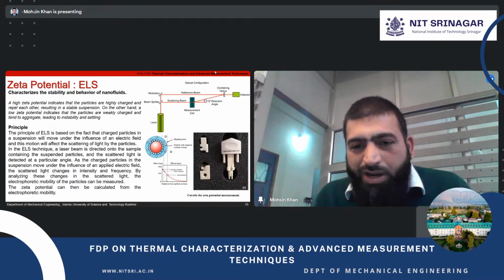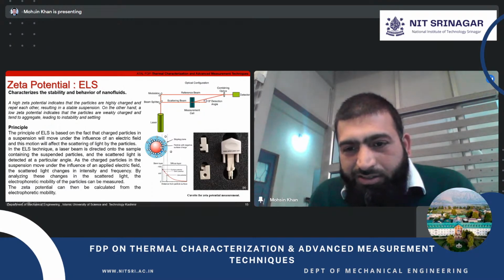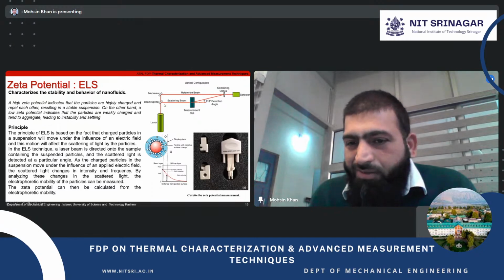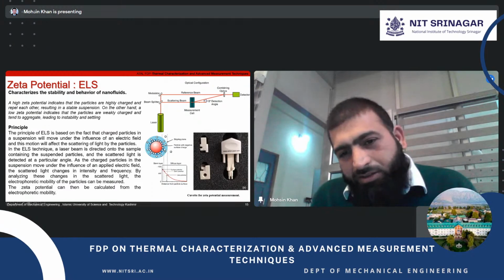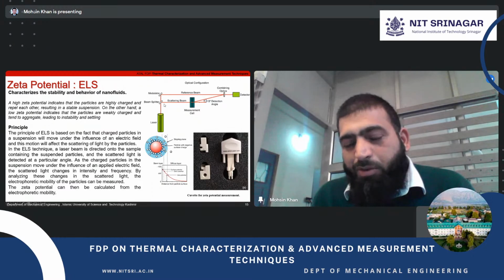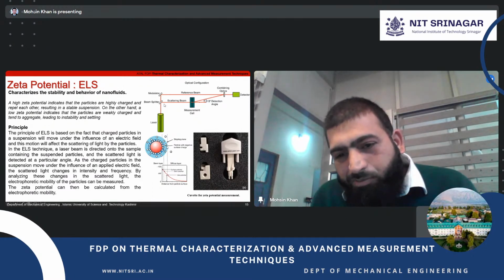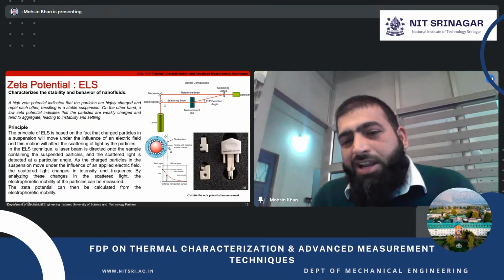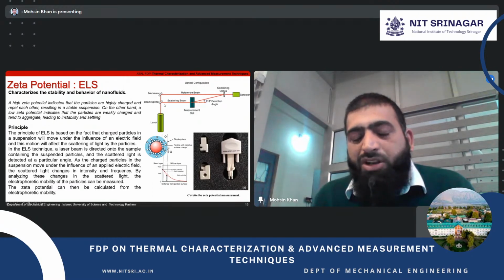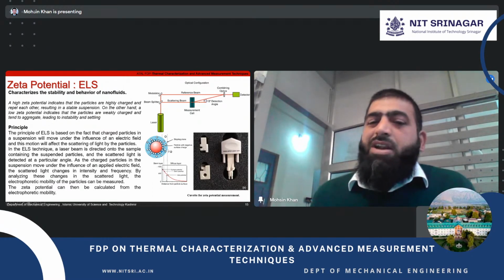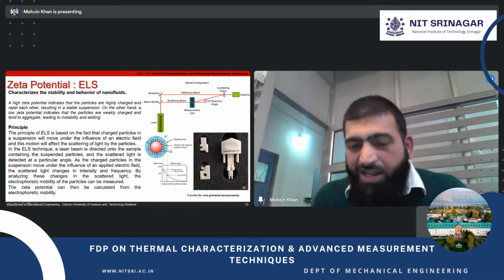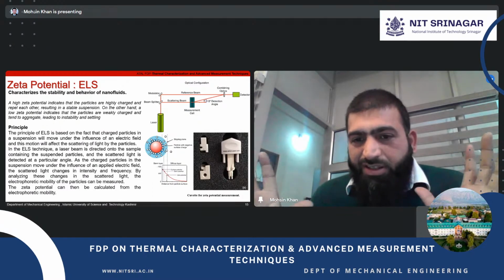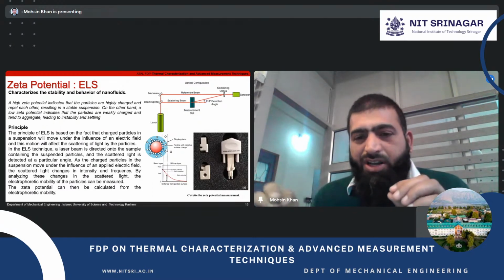Essentially, if you look at this picture, the center red particle is a particle with a negative surface charge, and the positive particles stick around it. This gets slightly lesser as we move away from the particle. The point at which the attraction is felt is essentially the zeta potential. The higher the zeta potential, the more stable the particle. That means if this width is more, the particle is in good contact with the liquid surface.